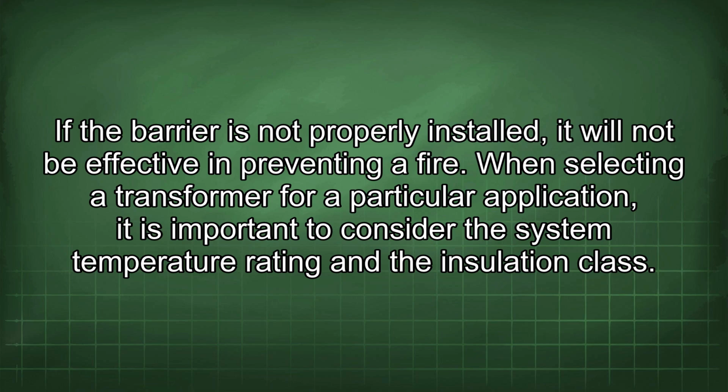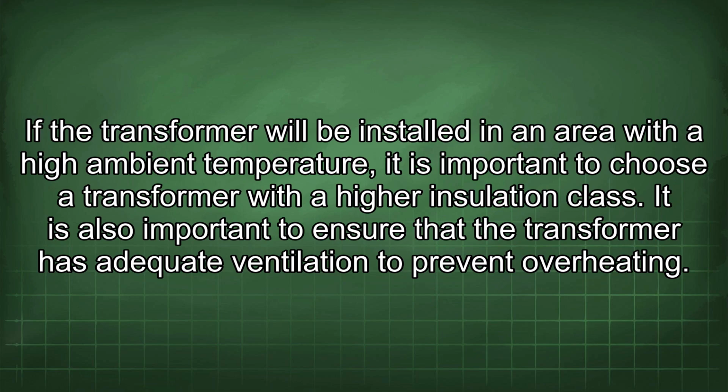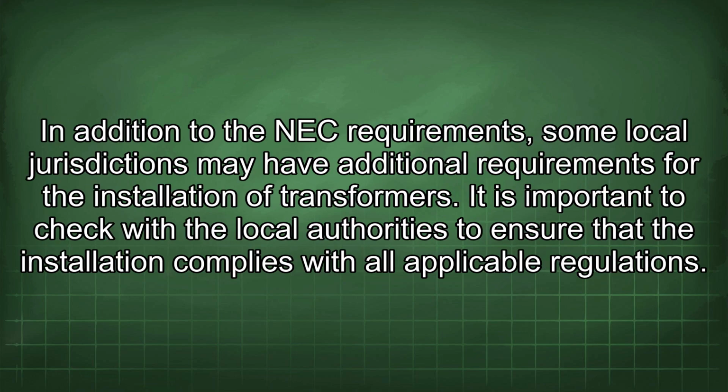When selecting a transformer for a particular application, it is important to consider the system temperature rating and the insulation class. If the transformer will be installed in an area with a high ambient temperature, it is important to choose a transformer with a higher insulation class. It is also important to ensure that the transformer has adequate ventilation to prevent overheating. In addition to the NEC requirements, some local jurisdictions may have additional requirements for the installation of transformers.